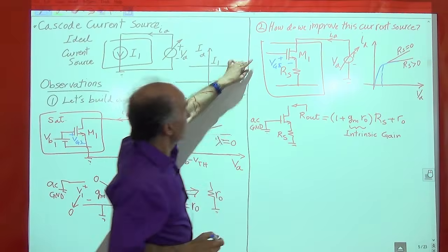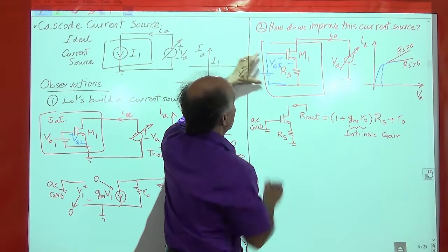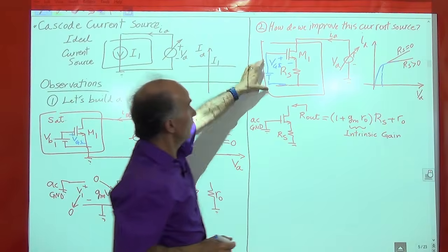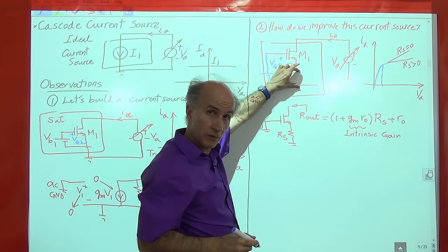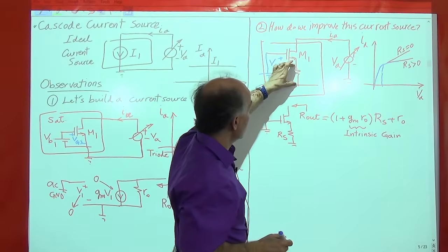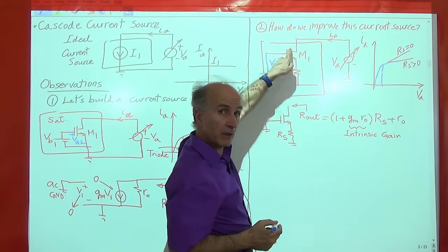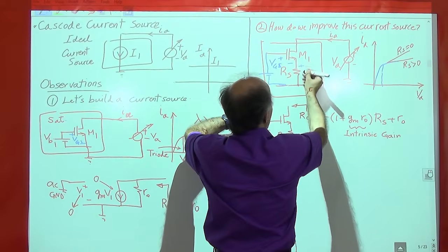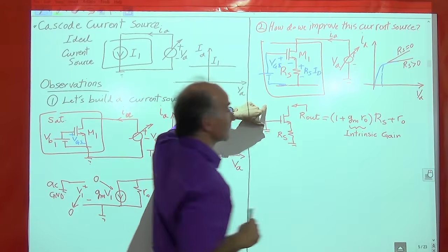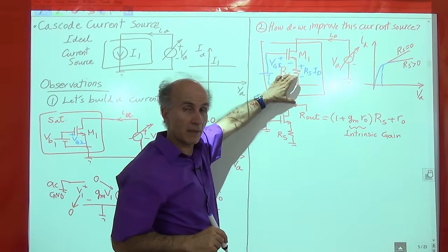So obviously this voltage, if I have a battery here, cannot be the same as this voltage because this new voltage is equal to VGS plus this voltage, right? KVL. So this has to be equal to this plus this. And how much is this voltage? It's Ohm's law. So we have RS times the current through this. So this voltage drop is equal to RS times ID. So the gate voltage has to be VGS plus RS ID, right?